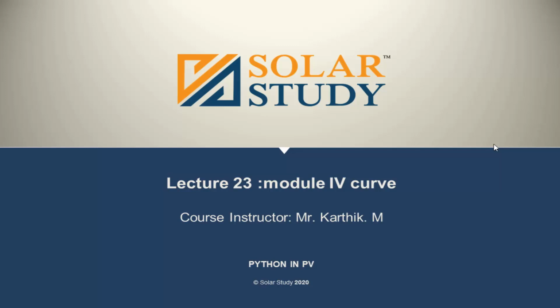First of all, modules are manufactured in the solar industry. They are fabricated and all the packaging is done. Before sending to the customer or before installing, they do some tests, called laboratory tests. This kind of test is called flash testing. After manufacturing, we can't put the module directly in the field, so before that they do the flash test. In the flash test, they inject radiation which is equivalent to the solar radiation.